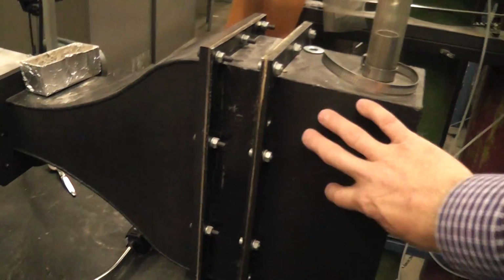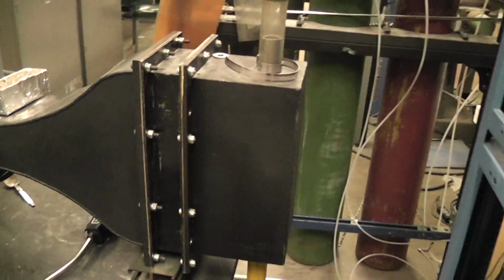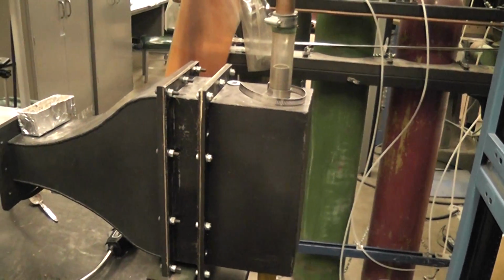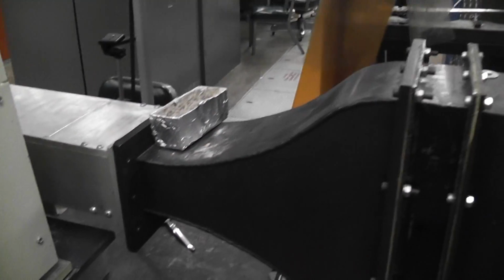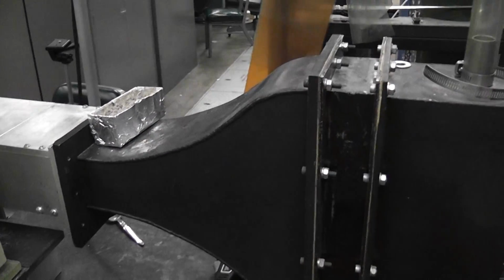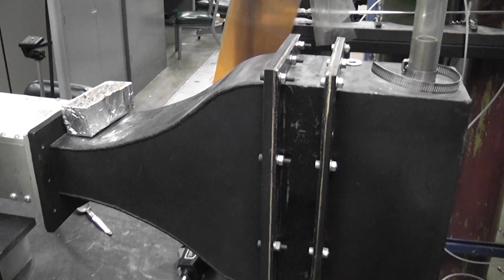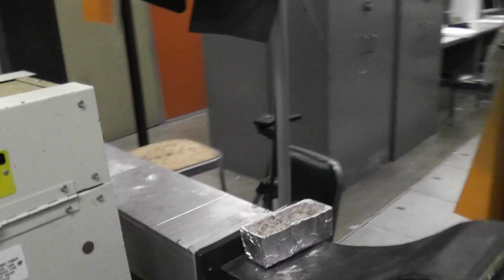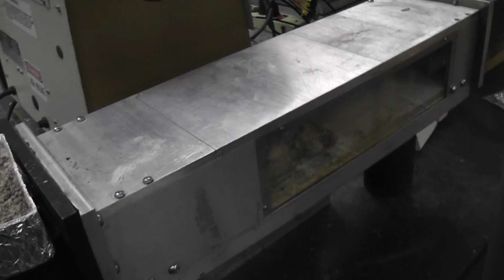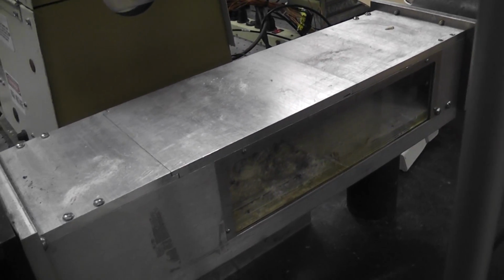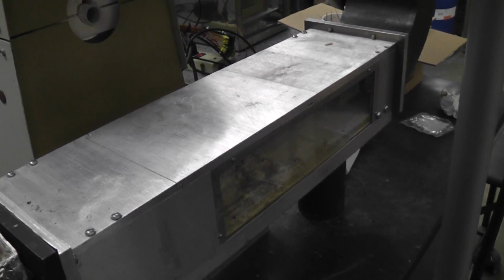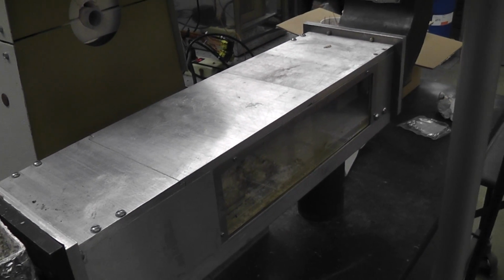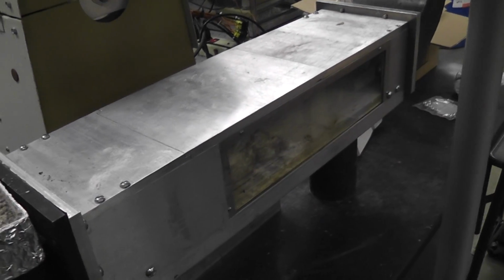Okay, so this section right here is full of a bunch of beads, and that's called a settling chamber. And then the air flows through this venturi, and the combination of these 2 elements straightens the air and gives you what's called a top hat profile as you go into this duct, which is the subject of some experiments that we're doing here in this lab. Okay, so that gives you a nice predictable inlet condition for the air to this duct.